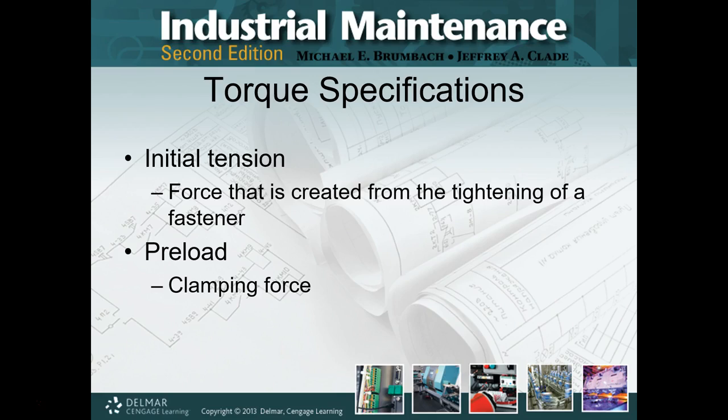And then as that rivet cools, it's going to shrink, and it's going to pull the two pieces of the boiler together. And that way the two pieces of the boiler don't move, and away we go. We know we've got the proper clamping force. The other area that you'll see this, because I also enjoy Art Deco, is some of the older buildings. Think of the Empire State Building. That was made with hot rivets, and it's the same principle.